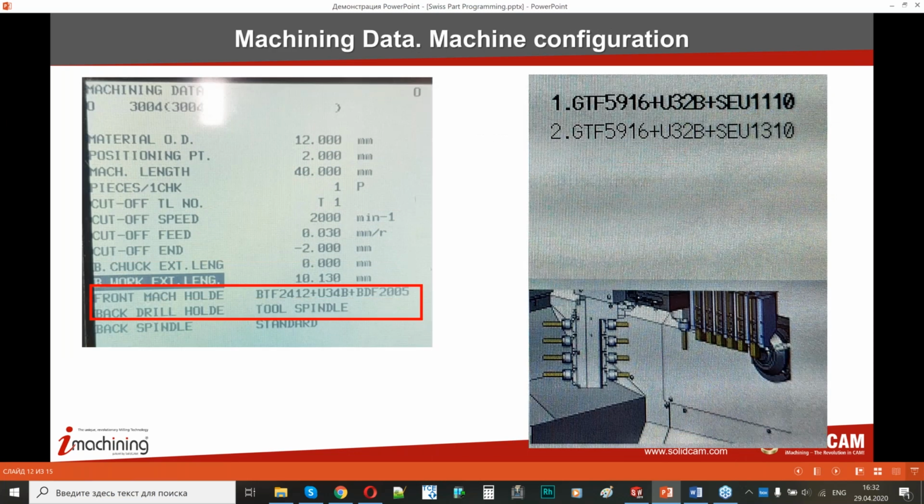The next set of parameters is connected with machine configuration. As I said, all machines have their own configurations, the number of attached blocks, and all tool blocks have certain names and numbers for the machine, and one machine can have a variety of tool blocks. You can buy a machine with one configuration and then add new blocks and improve machine capabilities. And you should give this information to the controller: what tool blocks will be used now for the current machine run?